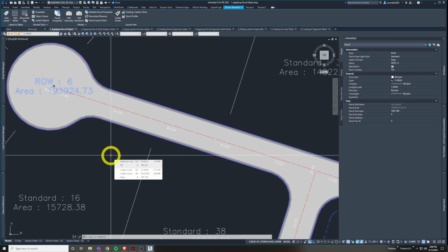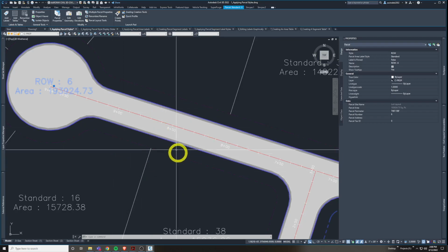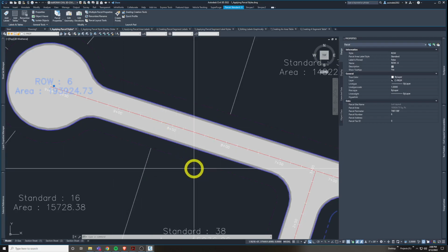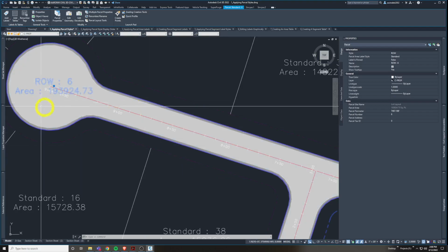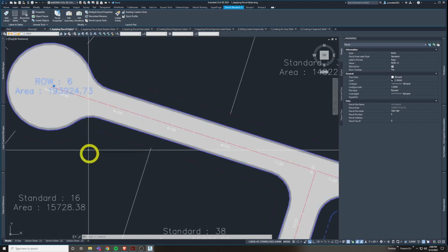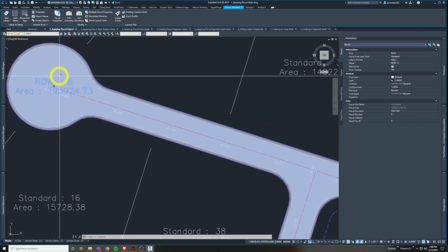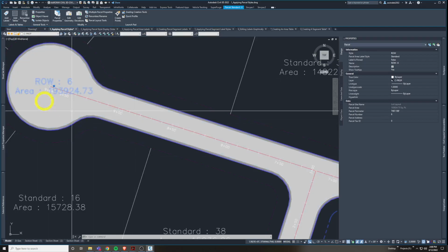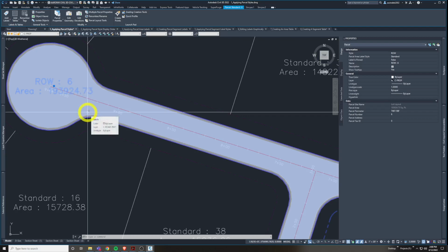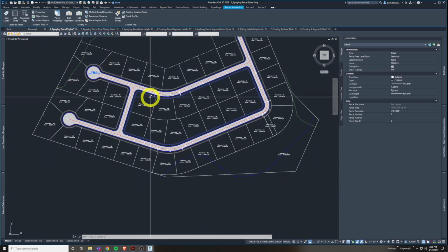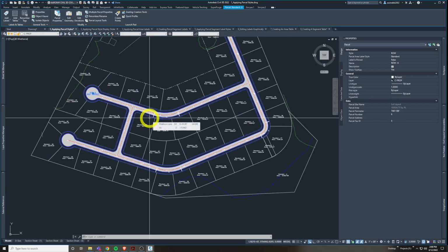That is a number if you're doing subdivisions or any kind of parcel dividing. You will have that memorized before you know it. But these parcel labels help make that quicker. You can add them to the parcel label so it shows acreage in square footage. They're nice things to speed up your production process depending on your needs and what you want to see, how you want to see it.